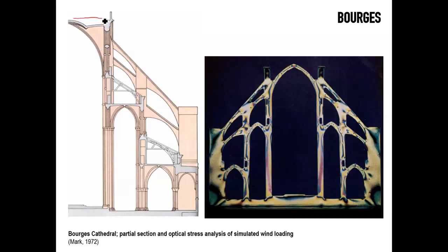There is normally a roof that sits above here, which we understand is a series of timber roof systems, rafters and trusses, perhaps sometimes in some cases. But the vaults themselves have a component of discharge of the weight. They are masonry structures that inevitably put a lot of horizontal thrust here in the structure.